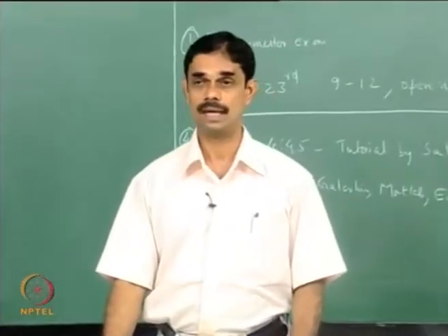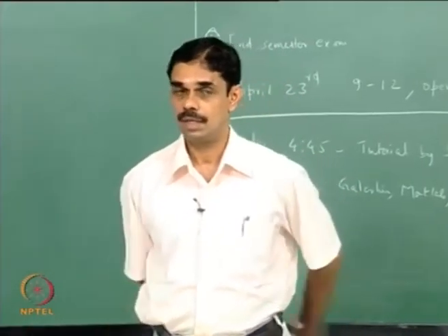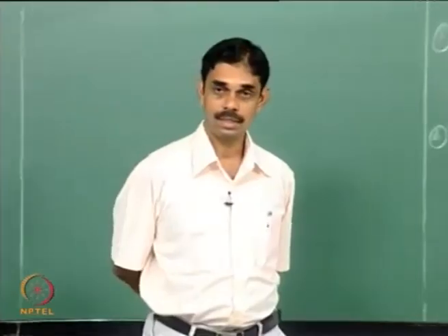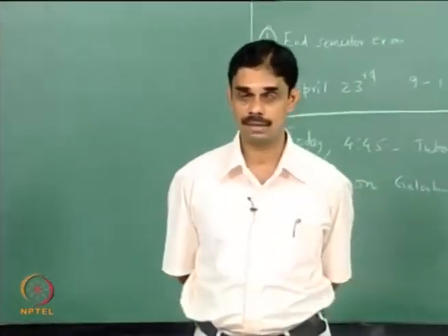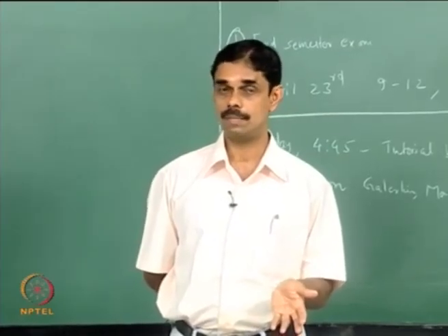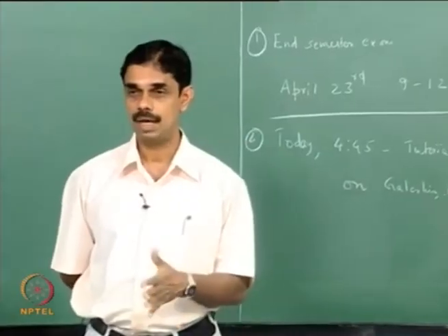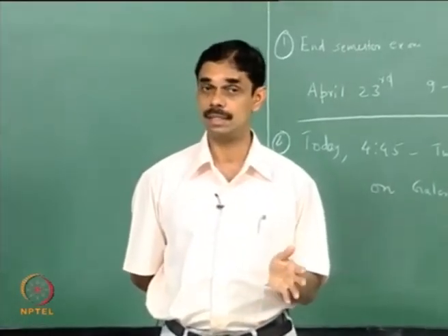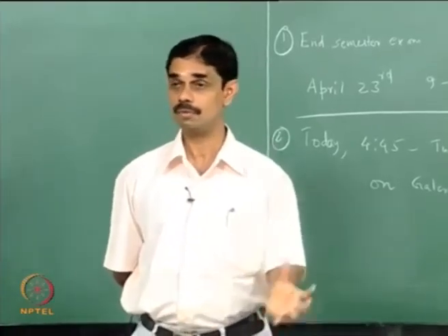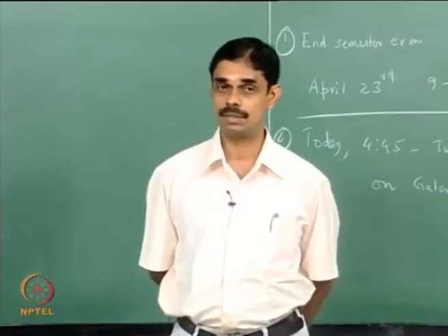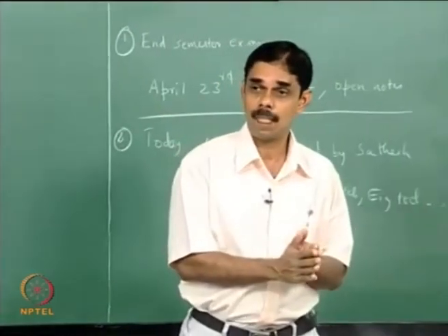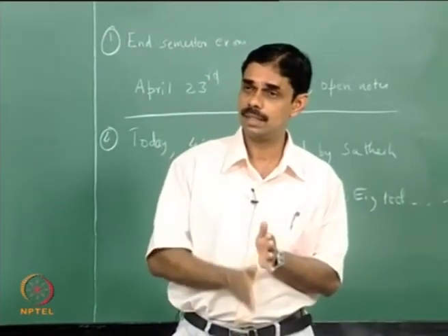So people looked at mechanisms with which NOx is formed and started thinking about how the mechanisms can be taken advantage of, to result in low NOx combustors. What happened is people found that you could burn under lean conditions, lean meaning fuel lean. So you have fuel lean combustors, but you cannot go as lean as you want. Why? There is some limit to how lean you can burn.